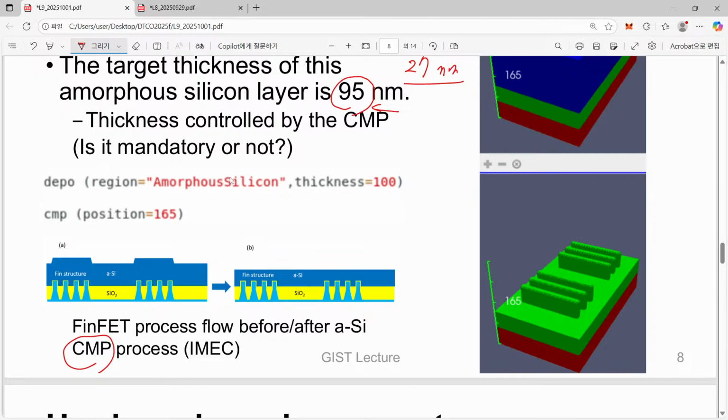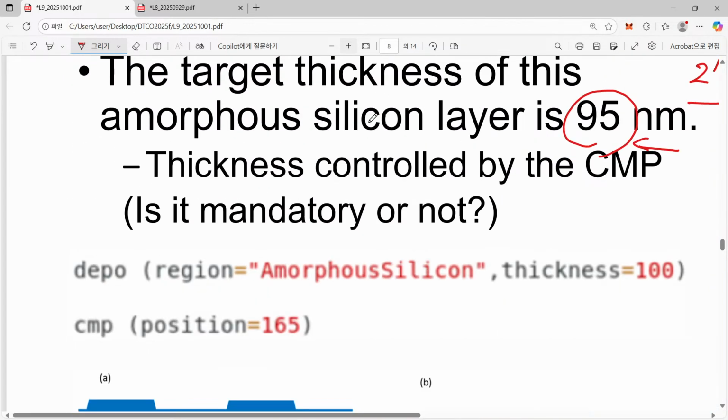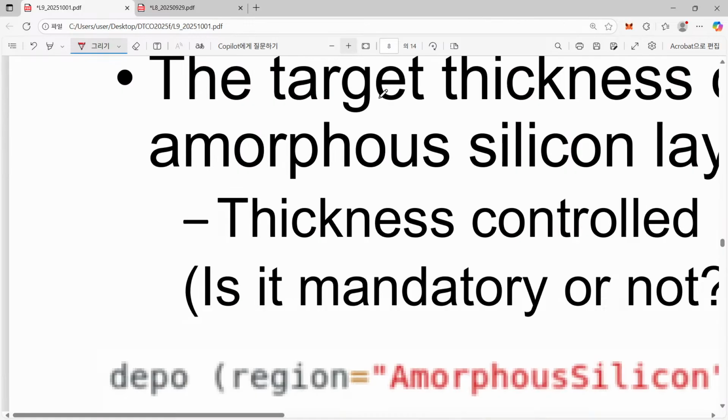So please have a look at this imec figure. At the beginning, we have this fin structure, and that is filled with this STI. This one is STI. Good. Up to now, we have done that. And previously, we just introduced dummy dielectric, this green one. Can you see it clearly? So let me just enlarge it as much as possible, so that this is, oh, good.